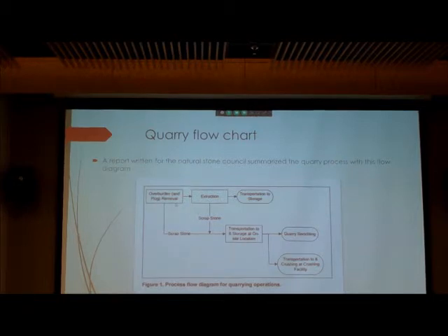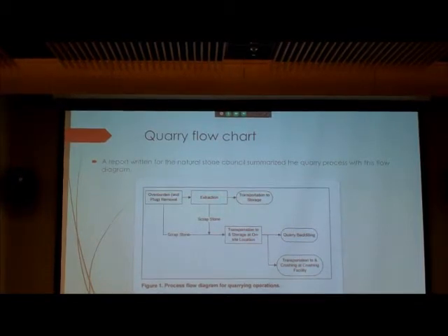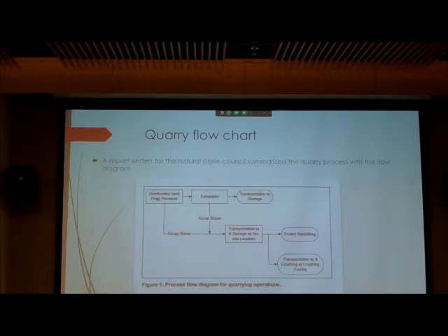Then you move to extraction. In the extraction process, a lot of how you cut the rock determines what you're going to use it for. So for instance, if limestone is cut with the flow of the source stone, it's called vein cut. And vein cut highlights the movements of the rock. Alternatively, if the block is cut against the vein, cross-cut, it creates a more uniform look for the stone. So it depends on what the quarry manager wants the stone to look like, on how they cut the rock out. It also depends on the type of rock.